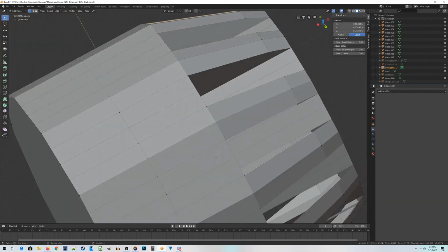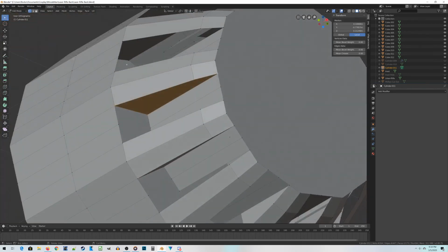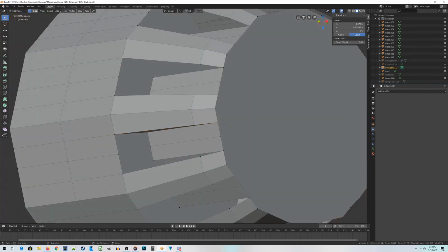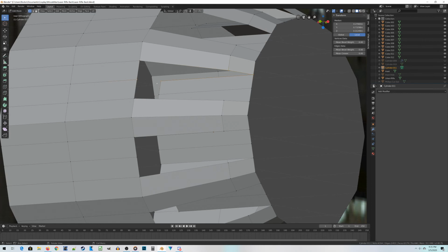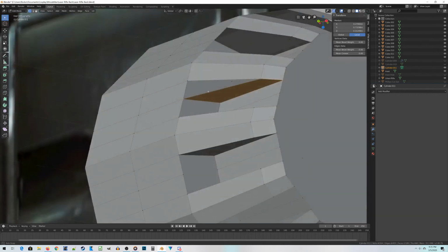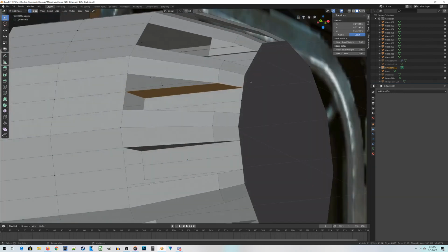If the face looks weird for some reason, that means you probably selected the wrong set of vertices. Just undo, select the correct ones, and keep going. Let me show you something. Let's say here, for example, I just selected the wrong vertex. If I create a face, you're obviously going to see something that looks weird here. That's kind of an example of what you would see if you screw something up. So that just gives you an idea. Or maybe I do something really weird, like, what if I select the vertex back there? See, that's really weird. So those are the kind of things you want to look for if you might have screwed something up. It obviously doesn't look right.